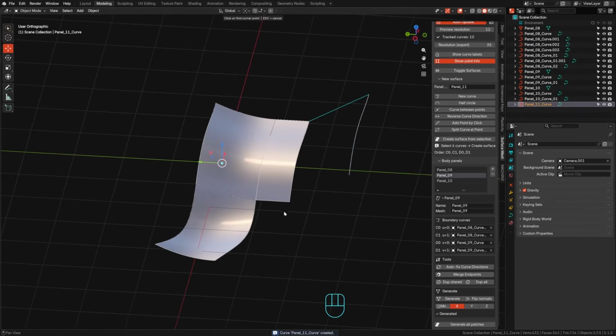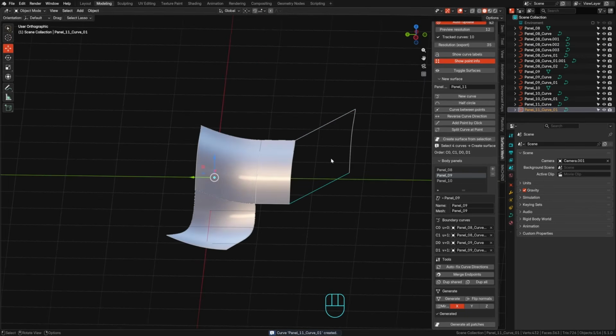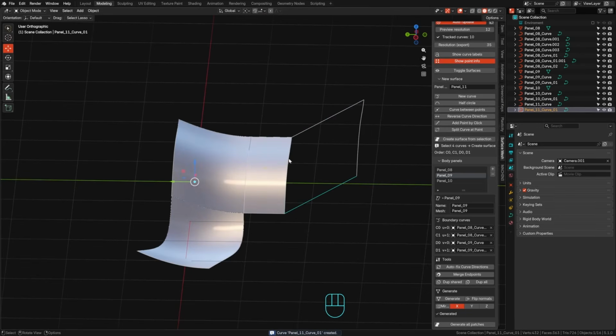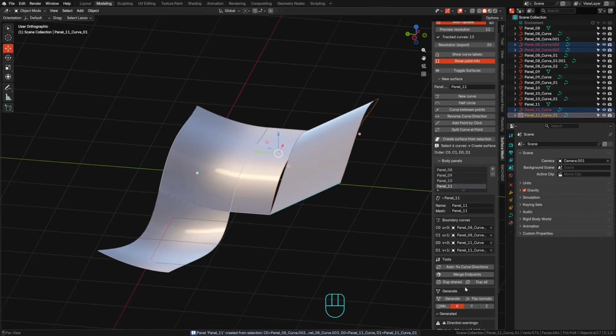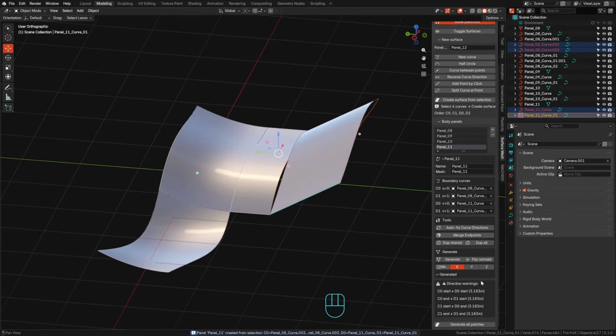Well, if I can manage it, I'll arrange the surface like this and connect it. It keeps repeating, obviously, it's very simple, so I just click, click. Now, when I select skip, these surfaces might behave. I'll generate the surface, yes, and now we see that error message. No worries, it's just that the direction of those curves is incorrect. Just click this button, and the surface will align to the desired shape.